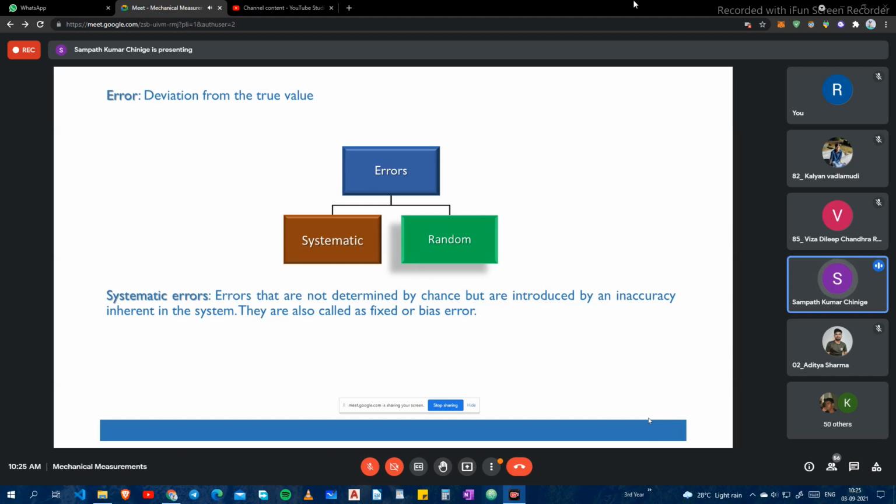He does not oil or lubricate it properly. There are certain moving elements in it that keep rubbing against each other, and over a period of time, if you are not lubricating it properly, dry friction will happen, and a gap will form between the mating or moving parts. Because of that, slowly you have an error that is consistent over a period of time.